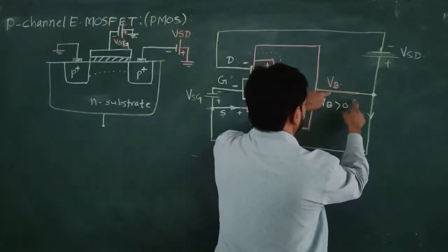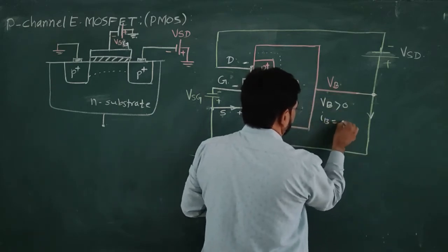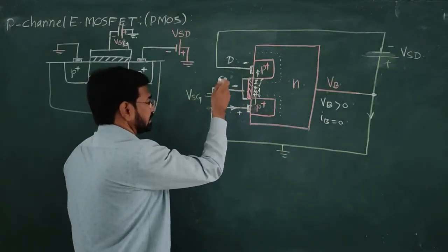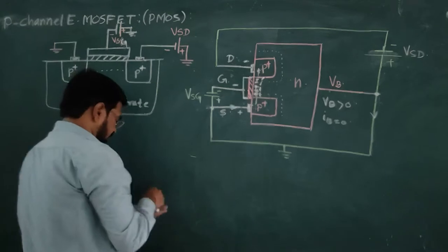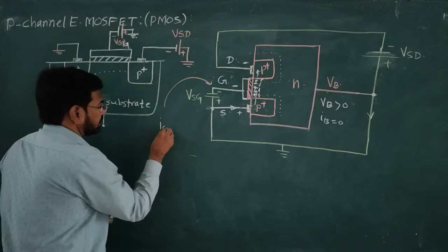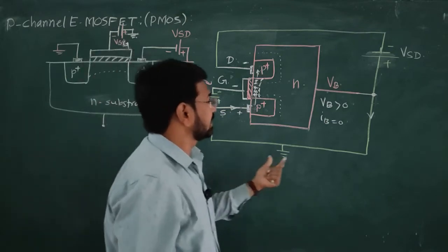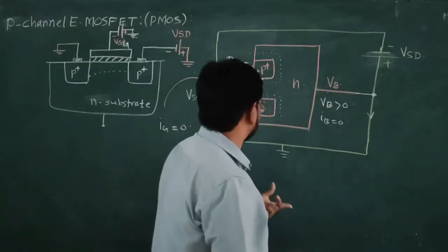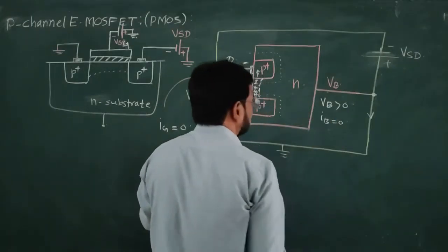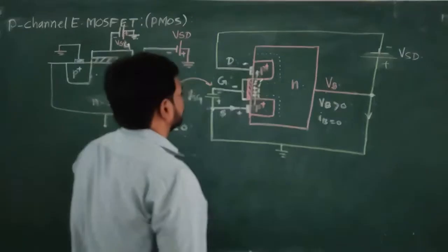Okay. But someone will ask what is the substrate current. So, IB, DC current, substrate current is 0. Now, what is the gate current? Gate current is also 0. Here we can make a point. You should remember this, that IG, DC gate current, is 0. Okay. So, this is the cutoff region of the device. We can make a statement that in cutoff state gate current is 0, substrate current is 0 and the drain current is also 0. Fine. So, these are the simple connections.